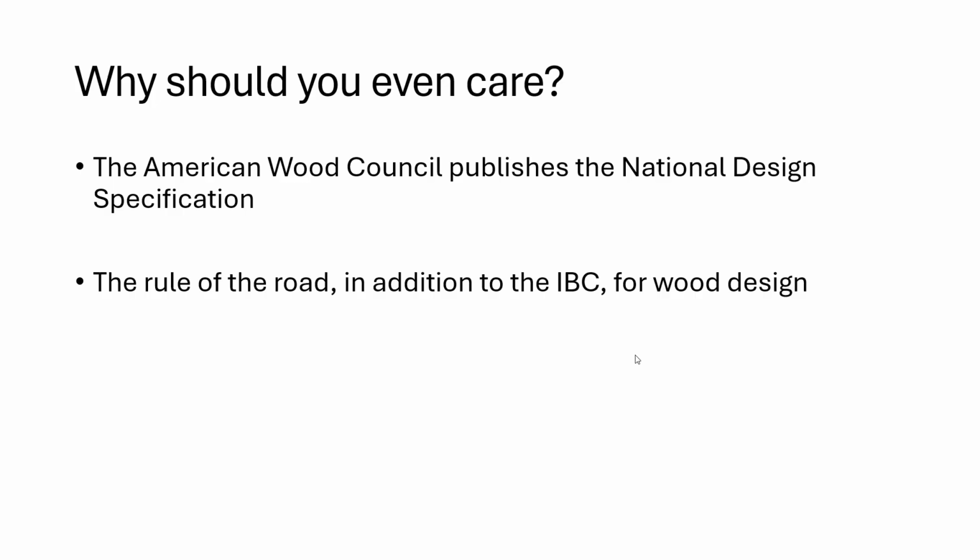So, with the IBC in mind, the NDS is the rule of the road for wood design and wood member analysis. But if there is a provision within the IBC that has a more conservative limit state, then you have to use that due to the code hierarchy.